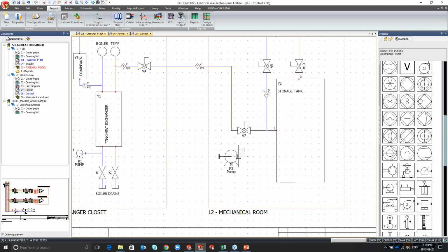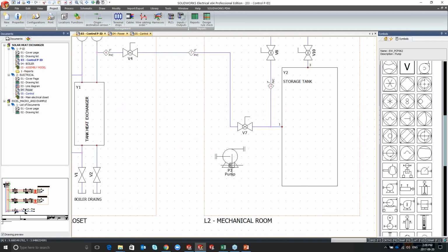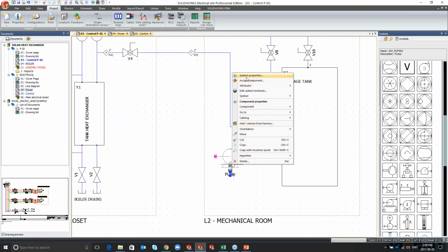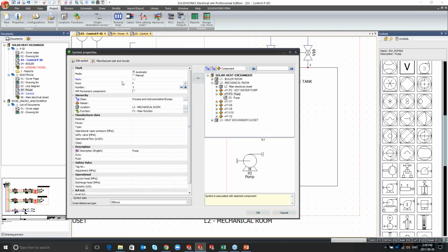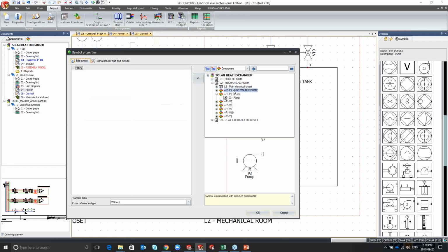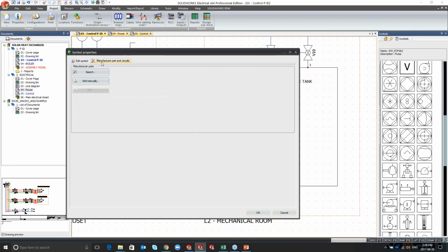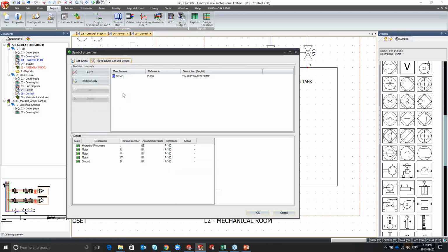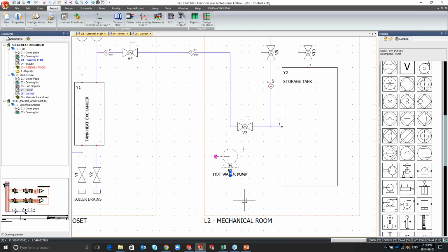So I can go ahead and instantaneously change this over, and if I click on pump 2, it will automatically inherit pump 2's properties and it'll become a perfect match. So I can switch the tags really easily, but the component ensures that it's always going to create new components and there's no duplication as you're inserting new components. So it looks like I've got my pump information over there.